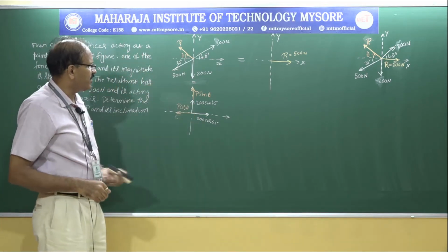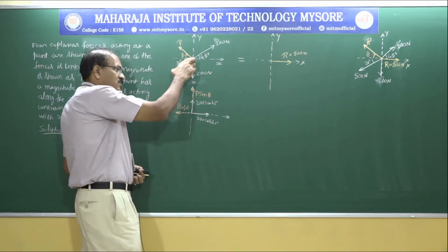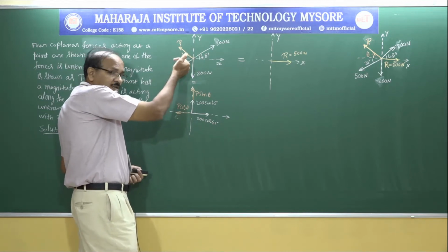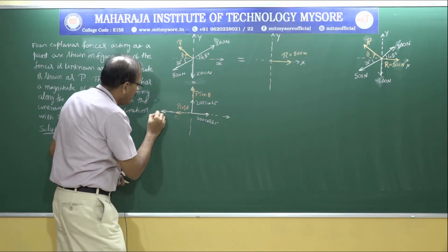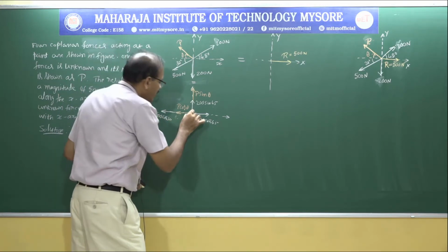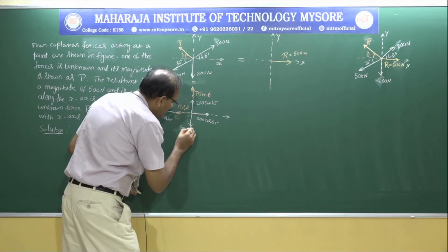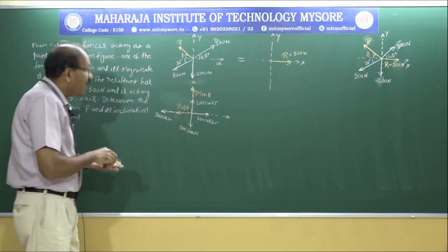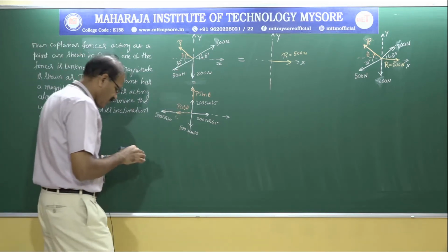Next, there is another force here, that is 500, with a horizontal component. If you rotate like this with the tail end fixed, the arrow is pointing to the left. So it is 500 cos 30, and the vertical component is 500 sin 30. Okay.